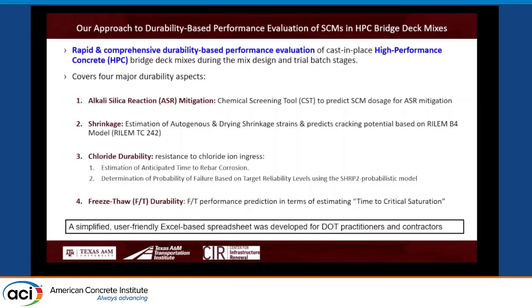So all the research that we did, our goal is to give you, the practitioner, a tool that can be used during mix design and trial batch stage. That means reducing dependency on the long-term durability tests. Some of the tests take 56, 90, 180 days. Can we design the mix in a very smart way? That's the goal. So we are covering the 4 major durability aspects to evaluate a mix.